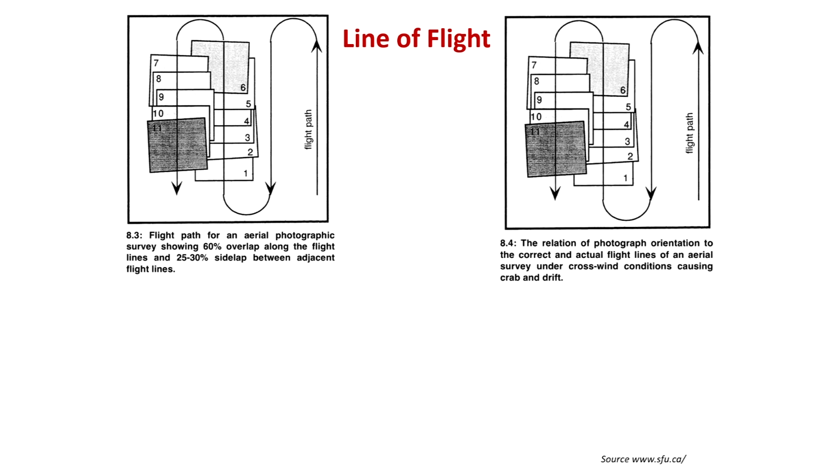So this is what has been explained here, that when you are flying in one direction, for example, this is the line of flight. Okay, so the flight is going like this, and it will collect the photographs, and if it's going back here, this will have 60% overlap. And whereas it is going sideways, this is another part. So this will have the 60% overlap.